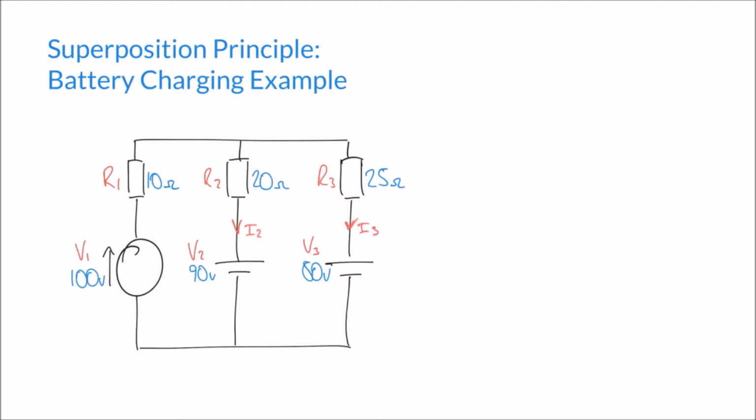So we've got to use the superposition principle in order to evaluate a circuit like this. Just like our previous examples of the superposition principle, we start by eliminating all but one of our power supplies and evaluating the circuit in a more simplified sense. Then we'll evaluate it with a different single power supply, and then finally a third power supply. And at the end, we can superimpose all of these results together.